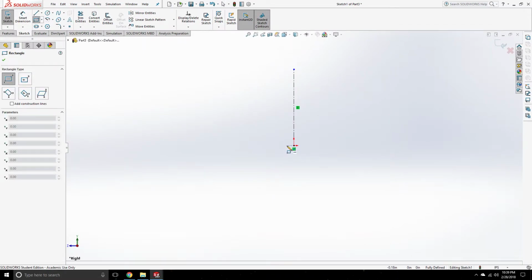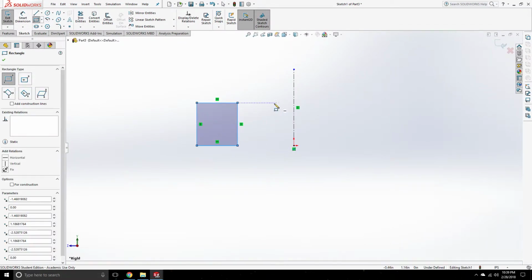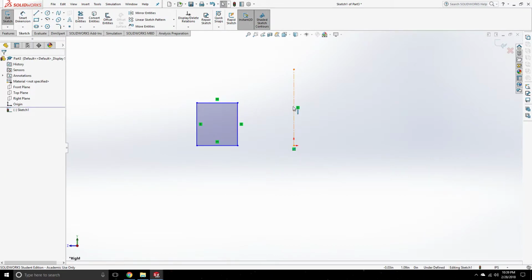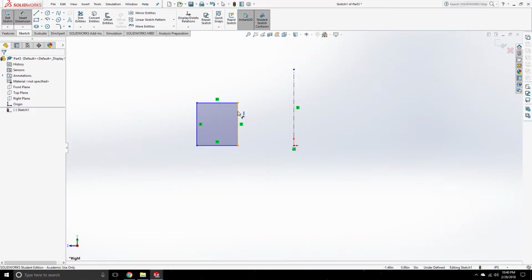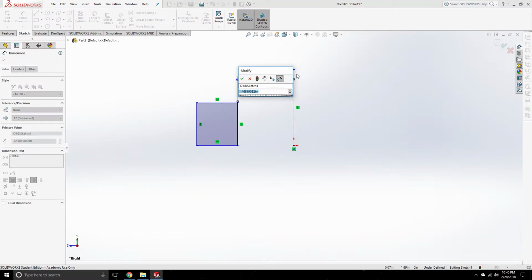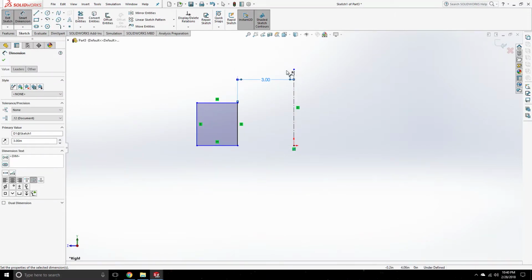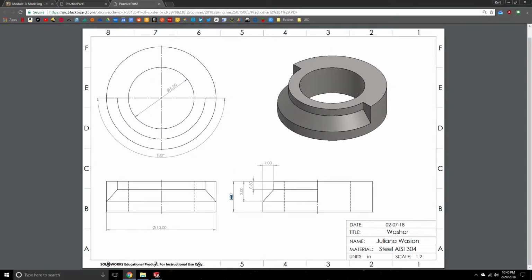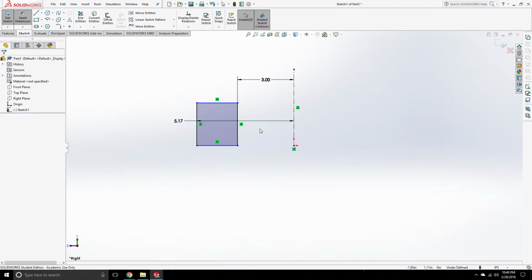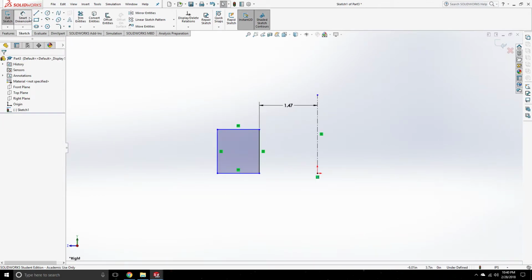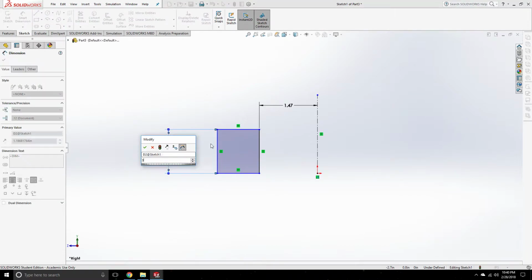So we're going to start by sketching this general rectangle, right? Because when this gets revolved around here, it's going to create that washer shape with this empty space in the inside. And we said that empty space on the inside needs to be 6. But once we revolve it, it's going to double. So let's create this empty space on the inside to be 3. Perfect. And then let's see other dimensions. Its height will not change when it revolves, so we can set that to be equal to 3. Oops, I got it set to that center line. We don't want that. So let me go back to Smart Dimension, make it 3.